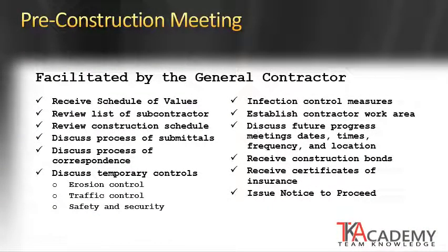After a project has bid, a construction contract has been executed between the owner and contractor, and the project has gone through a plan review and a building permit issued, now we're able to start a pre-construction meeting. The pre-construction meeting should always be facilitated by the general contractor. There are a lot of items that are covered in this, a lot of documents that must be transferred to begin the project.